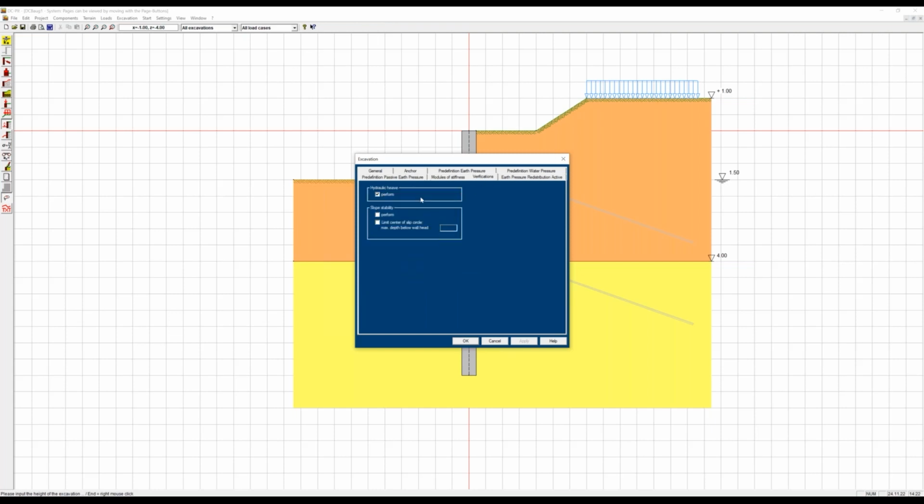For example, if we have different water levels, it's automatically checked if hydraulic heave could be a problem. And we can calculate the slope stability together with the program DC slope. But this should be, or mostly is, only calculated in the last excavation stage.